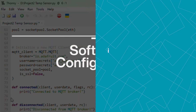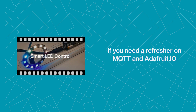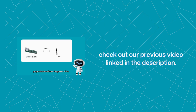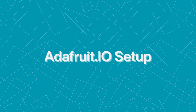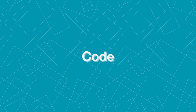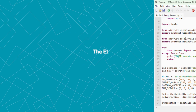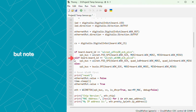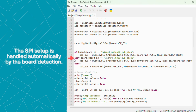For the software setup, if you need a refresher on MQTT and Adafruit IO configuration, check out our previous video linked in the description. In Adafruit IO, I've created 3 feeds: humidity, temperature, and formaldehyde to store our sensor data and set up a dashboard to visualize everything. Now let's look at the code. The Ethernet and MQTT setup is similar to our previous projects, but note that the W6300 uses QSPI. The SPI setup is handled automatically by the board detection.